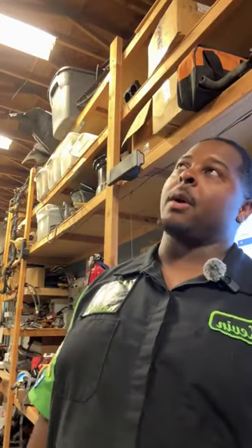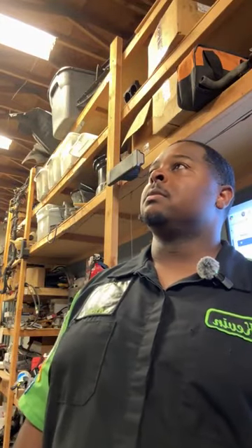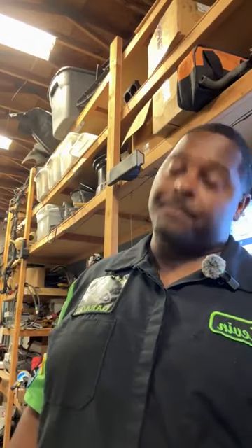I think I drove my truck for 4 days and it was completely falling on its face when giving it gas. It's stumbling. It only wants to idle. So I'm like, what the heck is going on? I was searching through a whole bunch of stuff. I'm like, there's no way. Ended up dropping the tank again to inspect that fuel pump. And sure as heck, that non-rated fuel line had burst. So my fuel pressure was just going through the pump, out of this little tube, back into the gas tank. Never making its way to the engine.